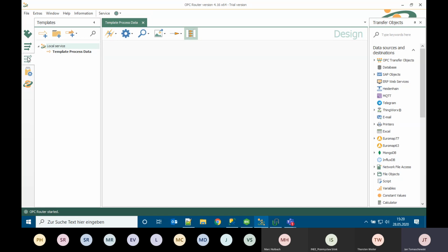But also if you have, for example, an MES application where you send production order data to a machine, and you have 100 machines in your company, and all the PLCs are programmed in the same way, you would always basically transfer the same kind of data. You could also use a template because it's always the same, just some placeholders or variables change for each instance. So those are the two purposes where we use templates.